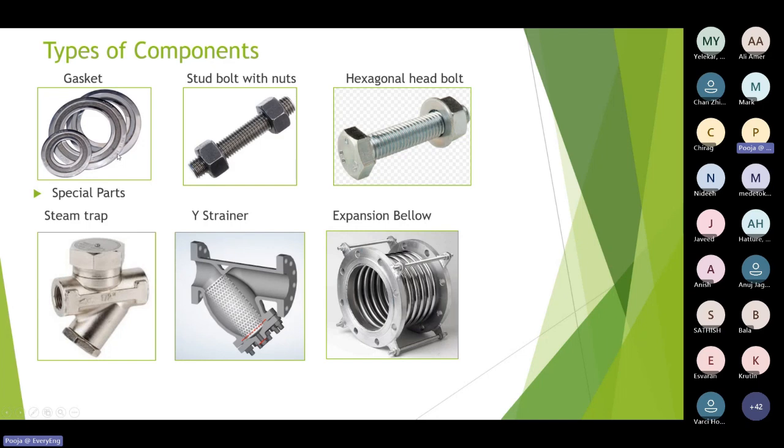It's mentioned here. This inner portion is also made of SS316. And this middle portion is made of some soft material. Sometimes it's made of graphite, sometimes PTFE. And as I said, when to use graphite, when to use PTFE. PTFE can be used only up to a temperature of 220 or 240 degrees Celsius. But for general purpose, we use this spiral wound gasket.